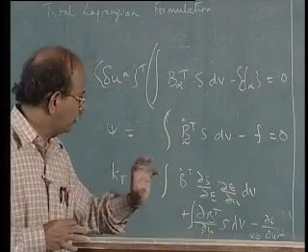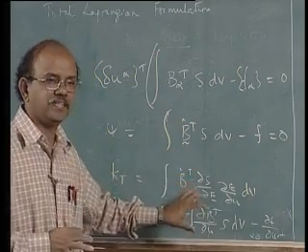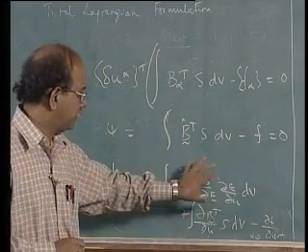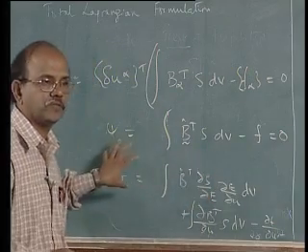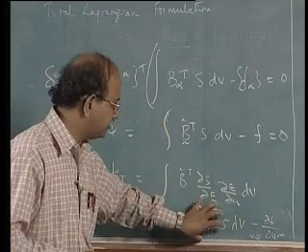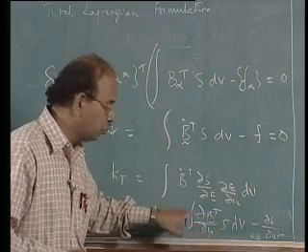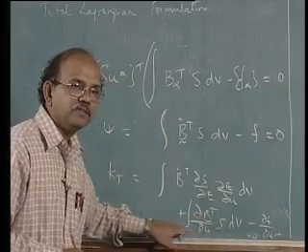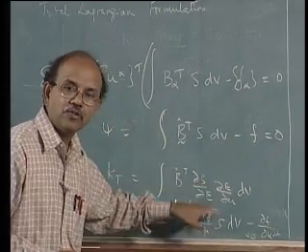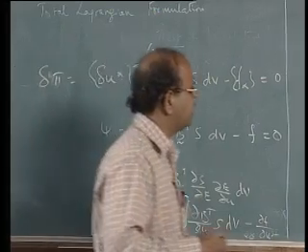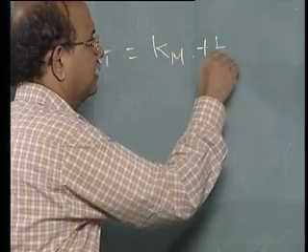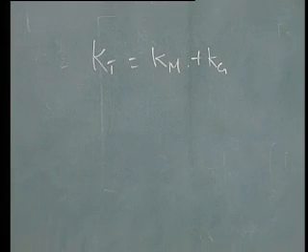That's the beauty of this whole formulation. You can understand each one of these terms. The first one is the material contribution to stiffness. The second term, note this, is due to B which has F in it. So this is what is called the geometric contribution for stiffness.